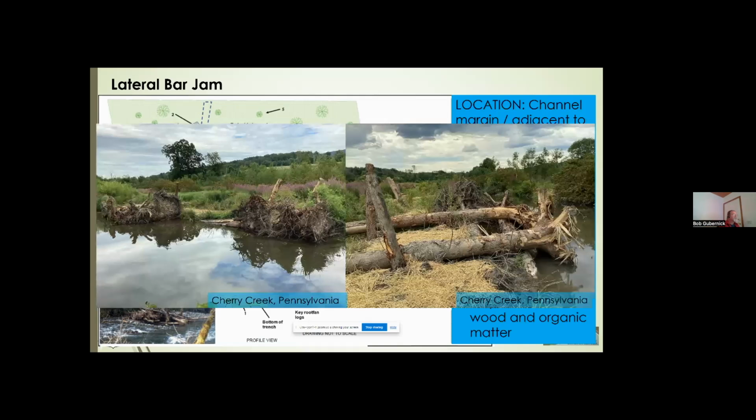And just an example from Pennsylvania for some recent ones that I built. And again, the size is scalable. In a low energy wetland type situation here where we're trying to narrow the channel, we're using the wood in here. You don't need to have a huge amount of ballasting the wood. There's not enough velocity, and with the piling and the weight of these things, it's really tough to move them. Plus, water doesn't get that deep across the wetland floodplain here. It's very large.